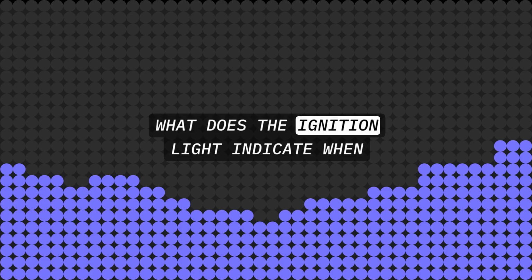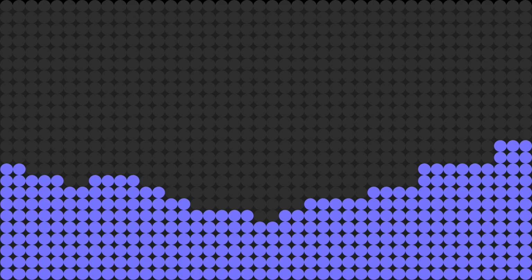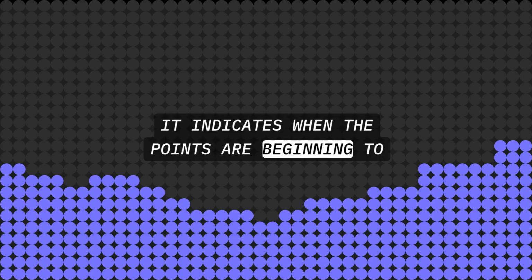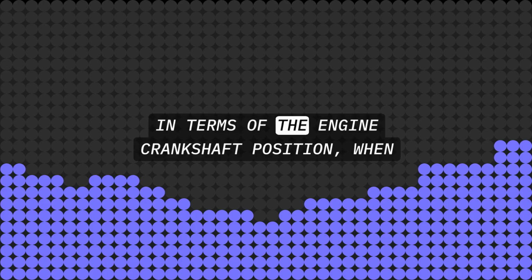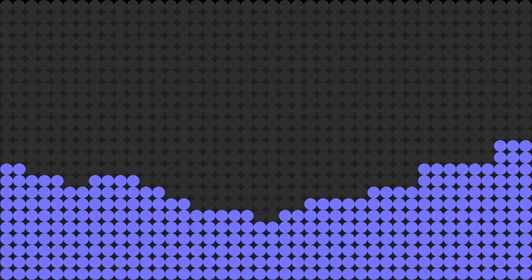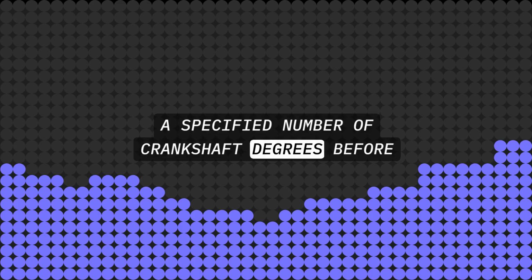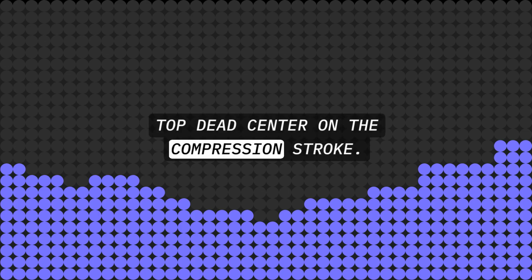What does the ignition light indicate when timing a magneto? It indicates when the points are beginning to open. In terms of the engine crankshaft position, when does the ignition event occur? A specified number of crankshaft degrees before top dead center on the compression stroke.